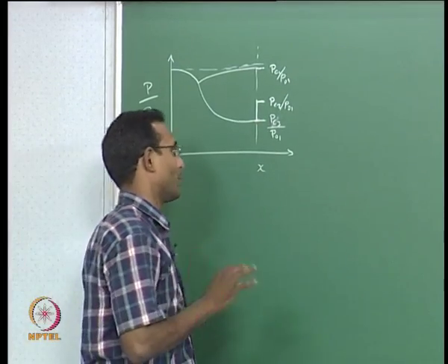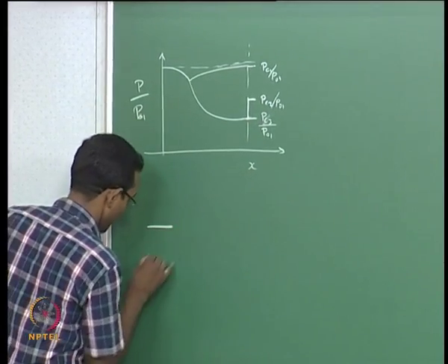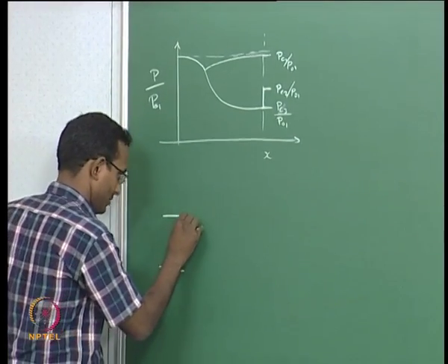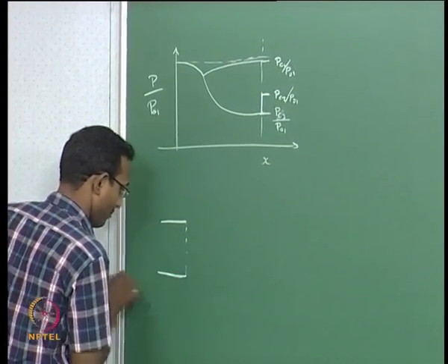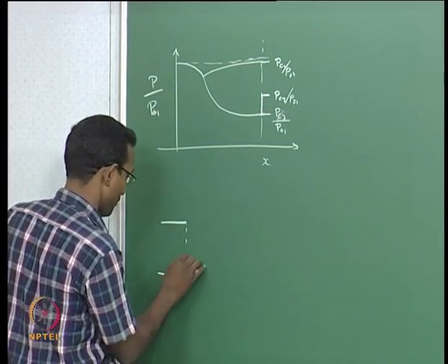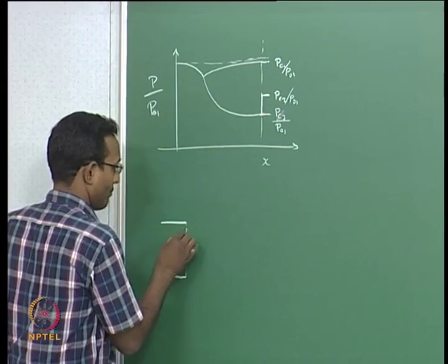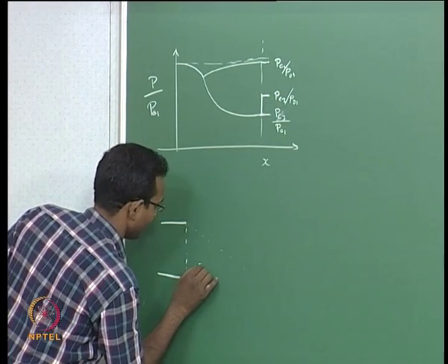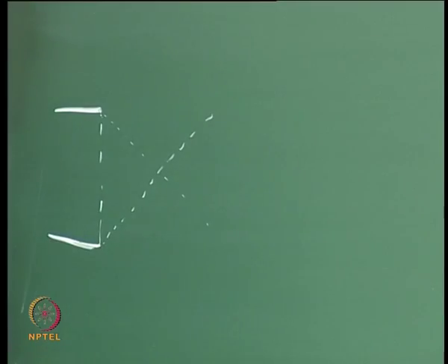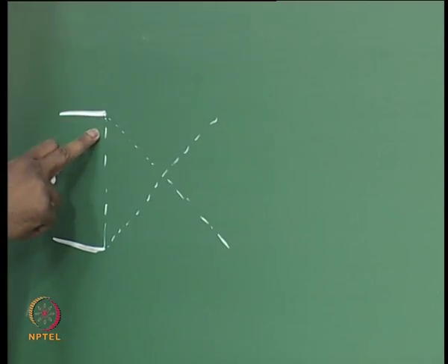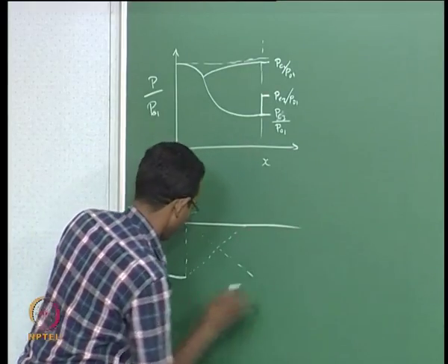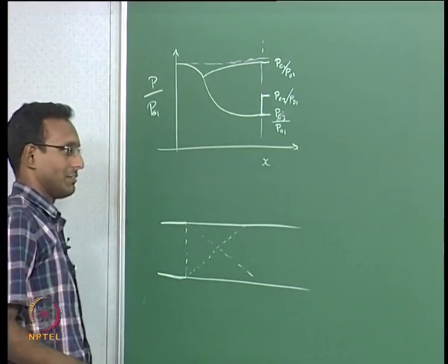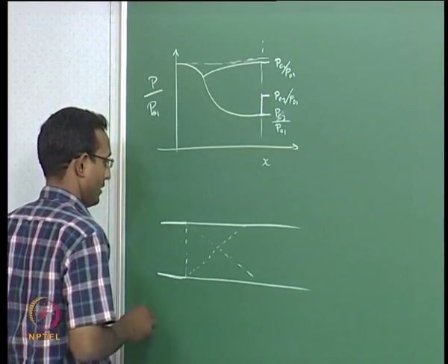Now we are going to start from that point, and I am going to say I have a nozzle exiting with exactly parallel walls, that is just for simplification, and I just barely have a Mach wave there. This is the condition I have. This is my Mach wave, and the pressures are equal on both sides, outside and at the exit, which means my jet will just go straight. There will be no difference. Jet will just go straight.